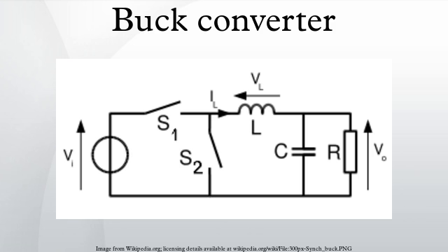Both static and dynamic power losses occur in any switching regulator. Static power losses include losses in the wires or PCB traces, as well as in the switches and inductor, as in any electrical circuit. Dynamic power losses occur as a result of switching, such as the charging and discharging of the switch gate, and are proportional to the switching frequency.